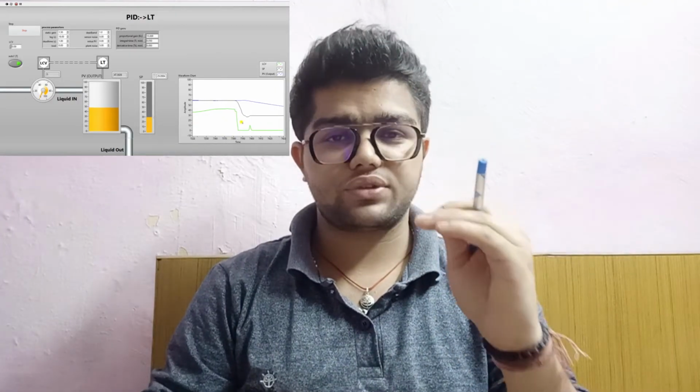We need to set a point. Like, I set the value to 60 and start it on auto, and it's automatic; after a few seconds, or a few minutes, depending upon your parameters, it tries to maintain the level. If you enter a set point of 30, it tries to maintain it between about 28 and 32. There's no need for any requirement to increase the temperature or ventilation to maintain the level. With the help of PID, we can easily control with the set point.